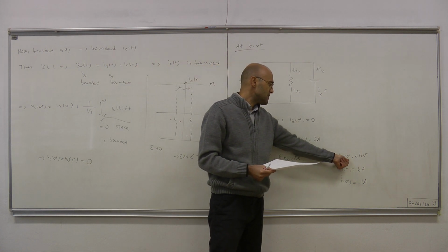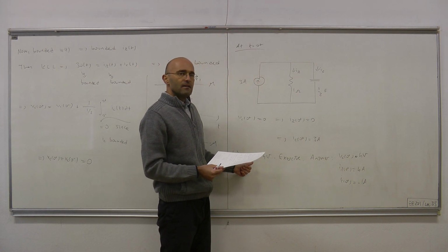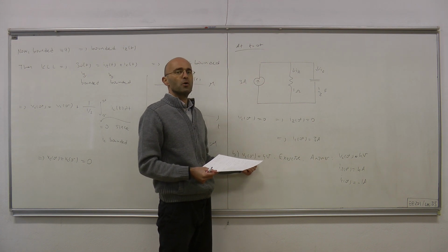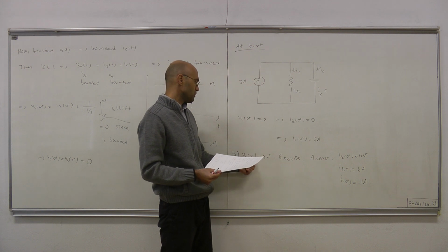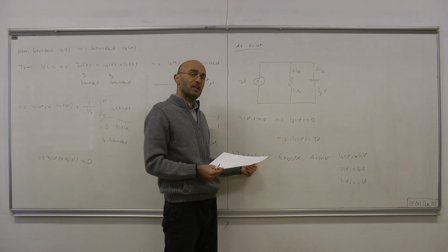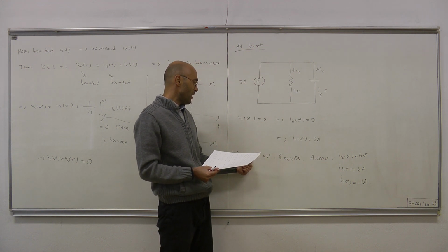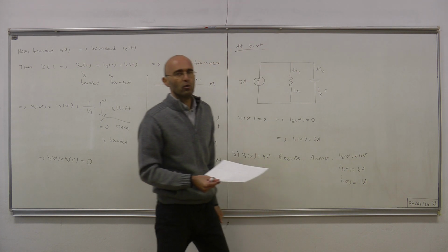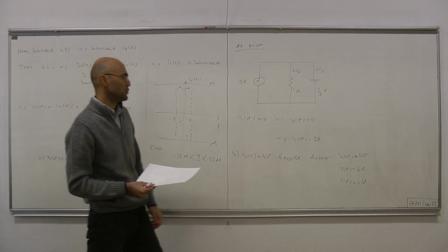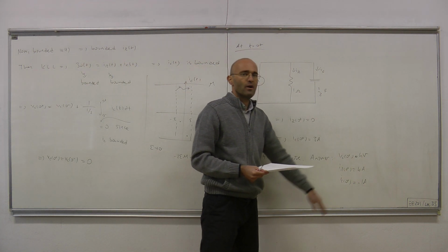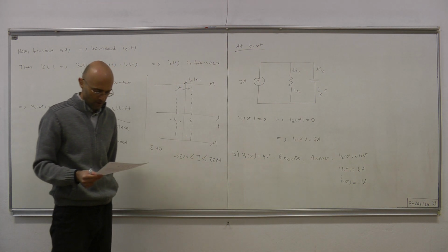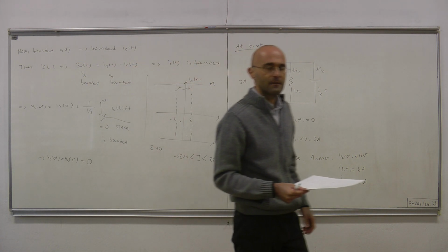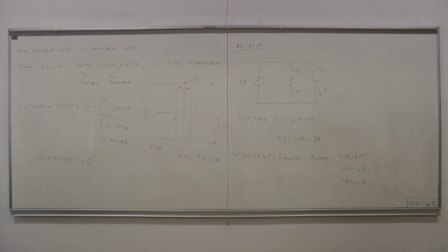Well, the important thing is that, again, using the same argument, because its current is bounded, the capacitor voltage will not experience any jumps. That is, if VC0 minus is 4 volts or anything, VC0 plus equals that thing. And once you have VC0 plus, you have everything at t equals 0 plus. Therefore, it's not really even an exercise, just a one-line solution.